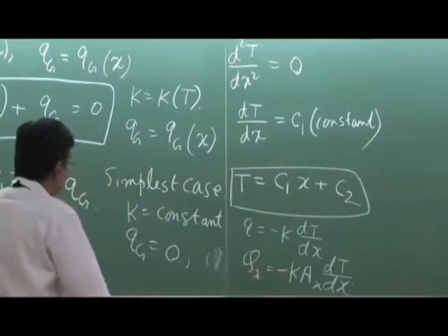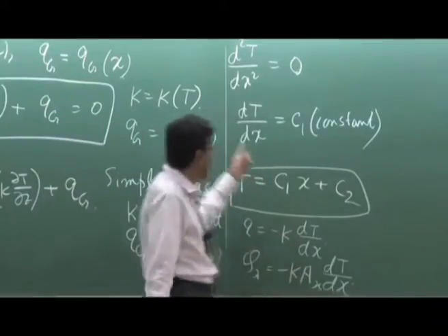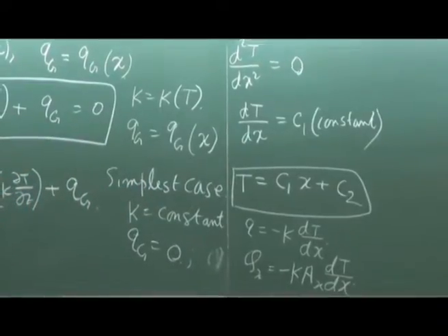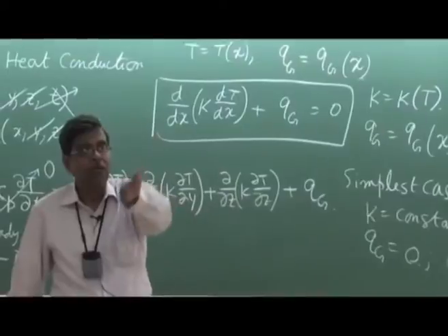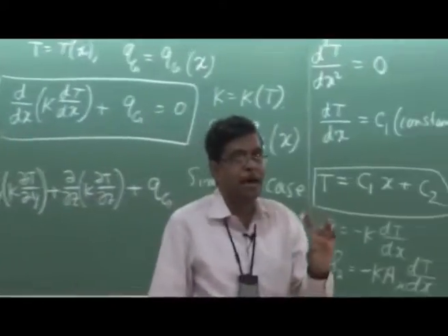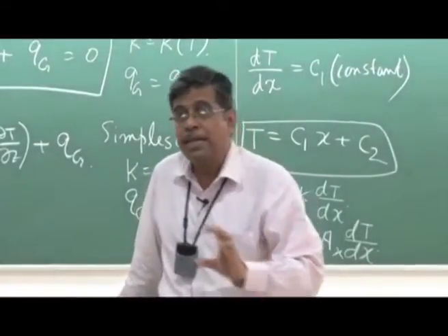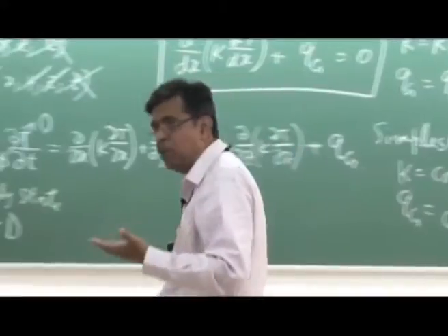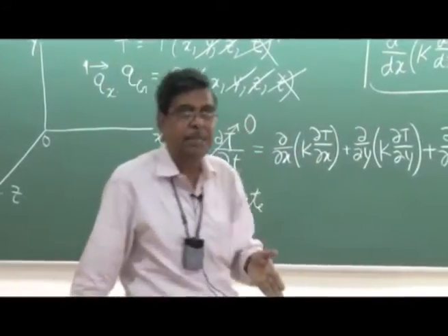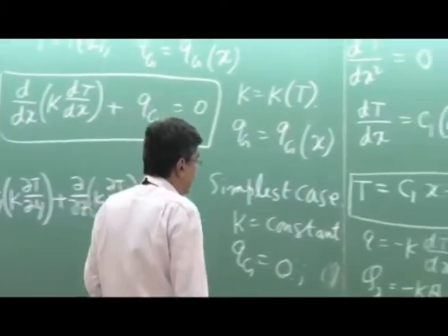So, therefore, it is not always necessary to write A, and in this case, the area for a one-dimensional problem is constant in the direction of heat flow. But sometimes, for a variable area which is truly not one-dimensional, we use an integrated approach that I will tell you in little detail afterwards, or we define an average temperature over a cross section and solve the problem as one-dimensional.